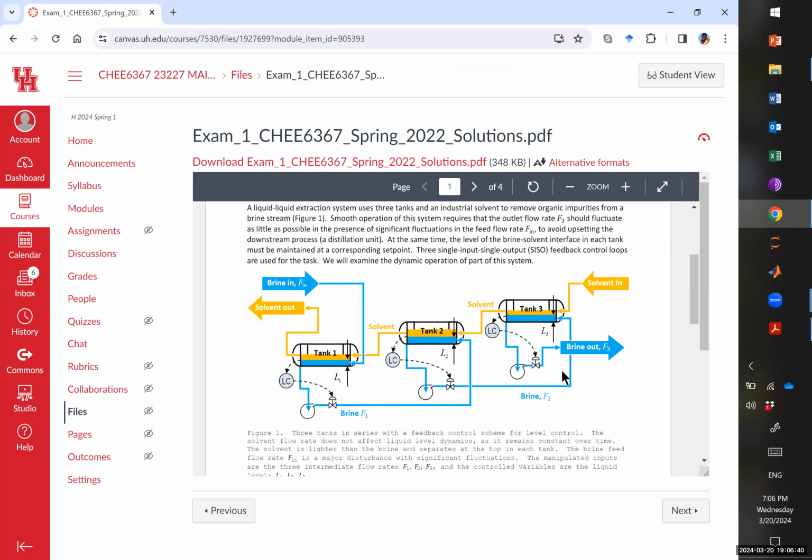One more question about this problem. Would you expect that if you tried to use the ultimate gain method, it would work? I don't know. Yeah, I tried, and it was very difficult to get it into an actual stable sinusoid. Yeah, the interesting part here is that it's not in the controller design, the control law part, where things become interesting. It's in the control structure. Essentially, you take the average height and you create a loop for that. It's a feedback loop for the average height.